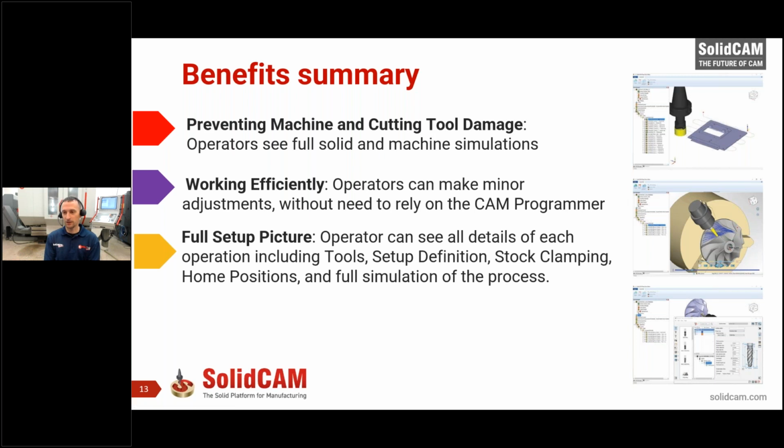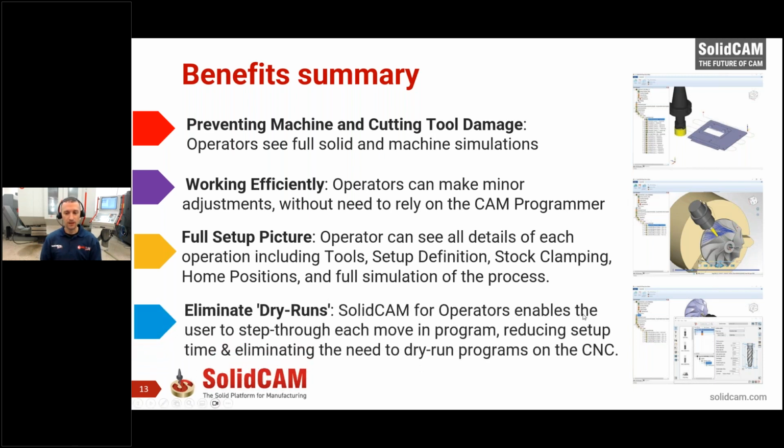It's actually something I forgot to mention, that as an operator, you also see where the work offsets are. Talking to everybody who's familiar with SolidCAM, you have the coordinate system manager from SolidCAM, so you can see where all the coordinate systems are inside. And you can either eliminate or speed up your dry runs.